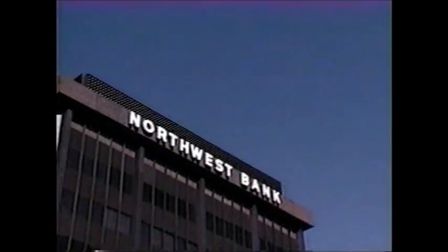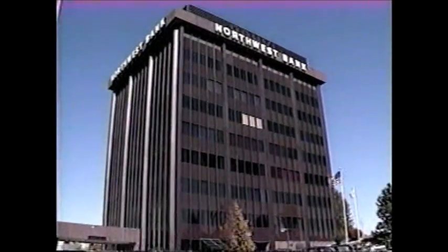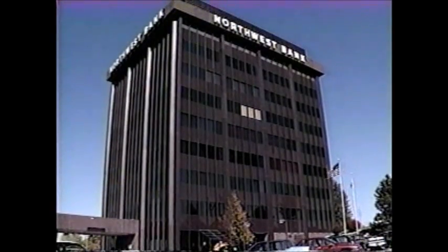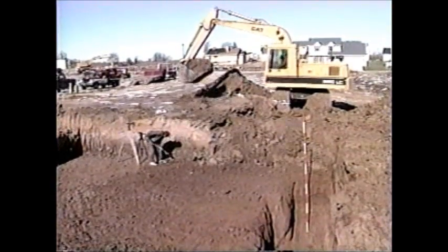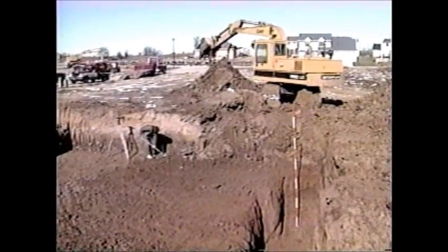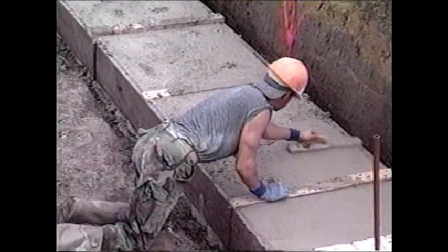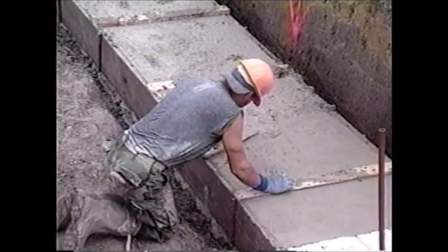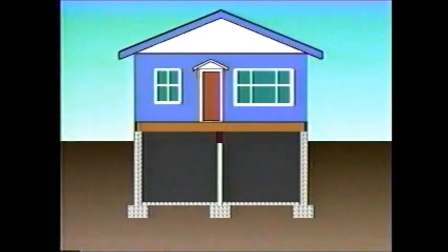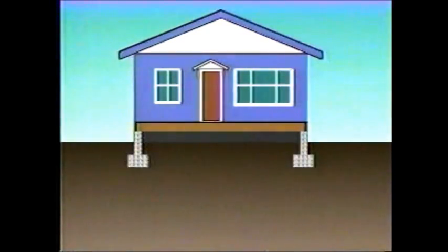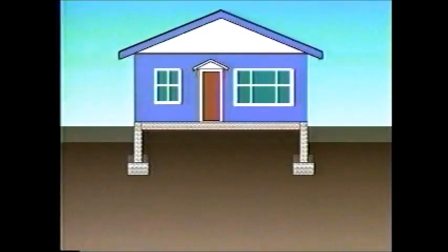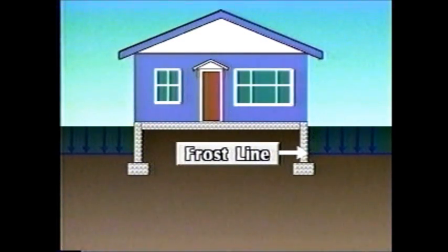What about bigger buildings? Well, depending on the soil, larger, heavier structures tend to be supported by either spread or pile foundations. If the soil is hard or near bedrock, a major structure may be built on a spread foundation, which places the weight of the structure on thick support walls. And depending on the depth of these walls, the space they create may serve as either a basement or a crawl space. However, in climates where the ground freezes in winter, they must be set below the frost line so that they won't shift when the ground shifts.